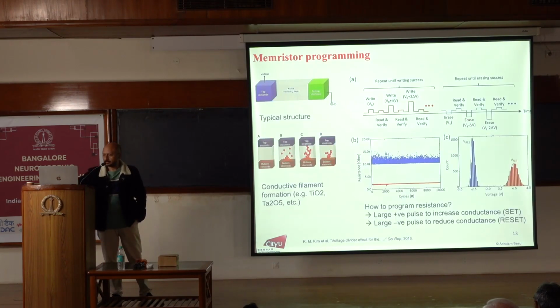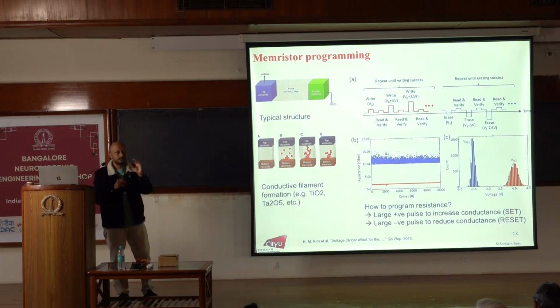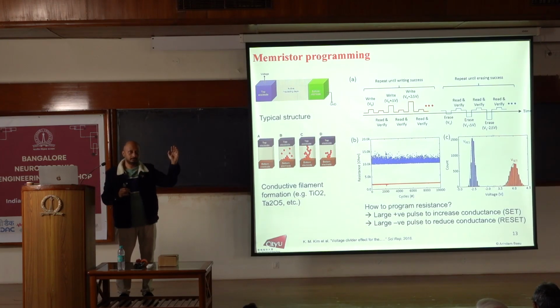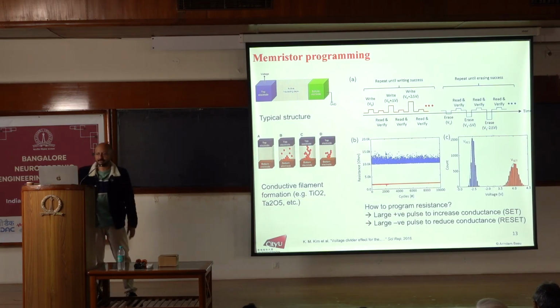With the insertion of this transistor, the gap between the zero state and the one state, suppose it's a binary resistance, will also be lessened, because of the on resistance of the transistor. The dynamic gap between 0 and 1 states comes closer. Ideally, the resistance in the off state of the MOSFET is a very small conductance, or very big resistance, whichever way you want to see it. That will push these two curves far apart, because the off resistance of the MOSFET is very high, so it pushes the off part higher. That's the reason you're using the selector.